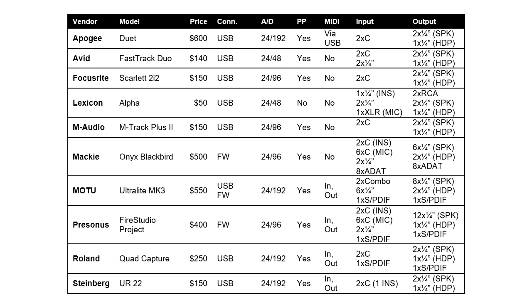For each microphone, XLR or combo, input connector, there is a corresponding microphone preamp in the unit. The quality of the preamps is one of the factors influencing the price of the unit, but not the only one. Other factors include, in no order, the number of connectors, the quality of the AD and DA converters, the presence of digital meters, and the inclusion of a MIDI input and/or output connector.